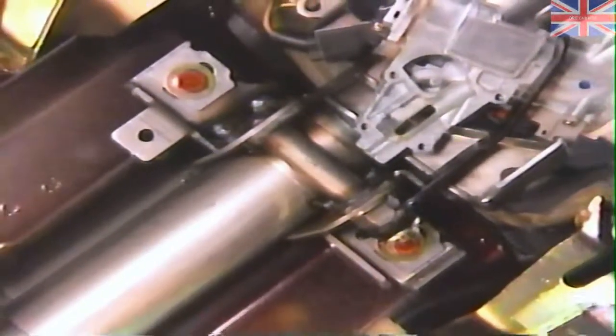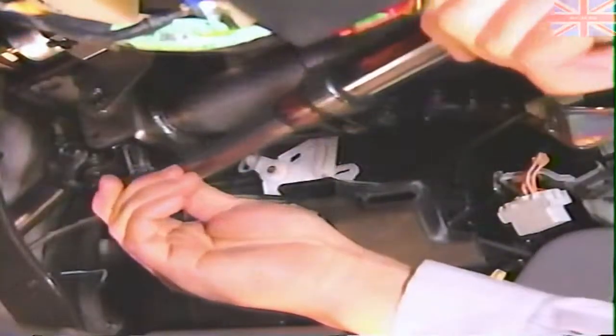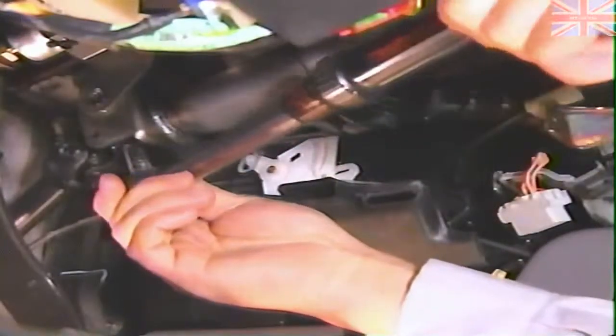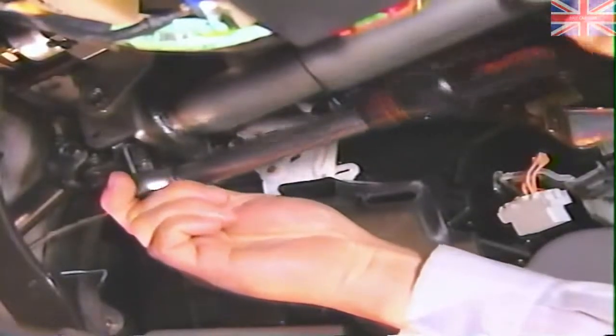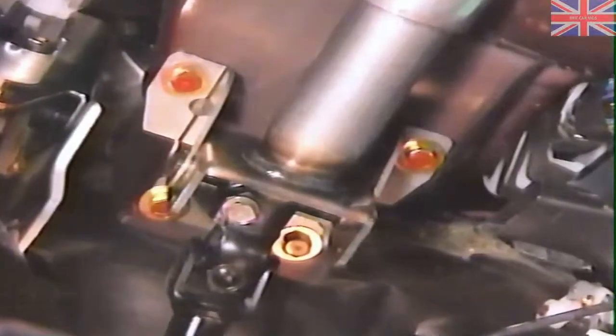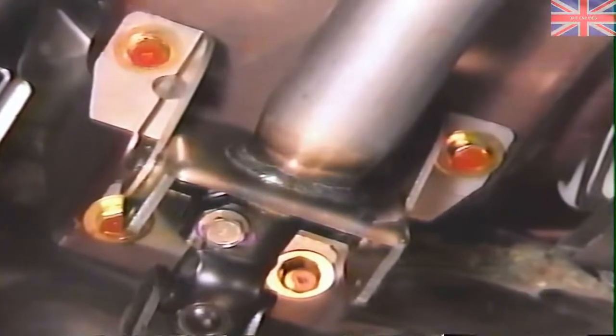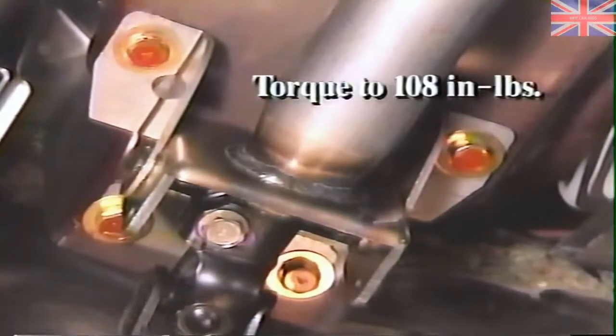Install the 2 upper mounting bolts without tightening them. Then install and tighten the pinch bolt that holds the steering shaft to the intermediate joint, tightening it to 156 inch-pounds. Install the 4 lower steering column mounting bolts and tighten the upper and lower mounting bolts to 108 inch-pounds.